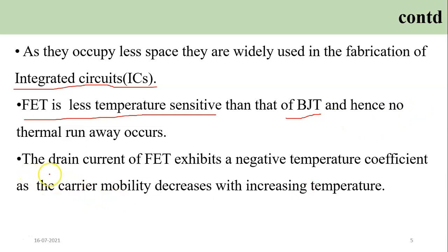And similarly, the drain current of FET exhibits a negative temperature coefficient. Very important. What is the meaning of negative temperature coefficient? As the temperature increases, the drain current decreases. That is because the carrier mobility decreases with increase in the temperature.